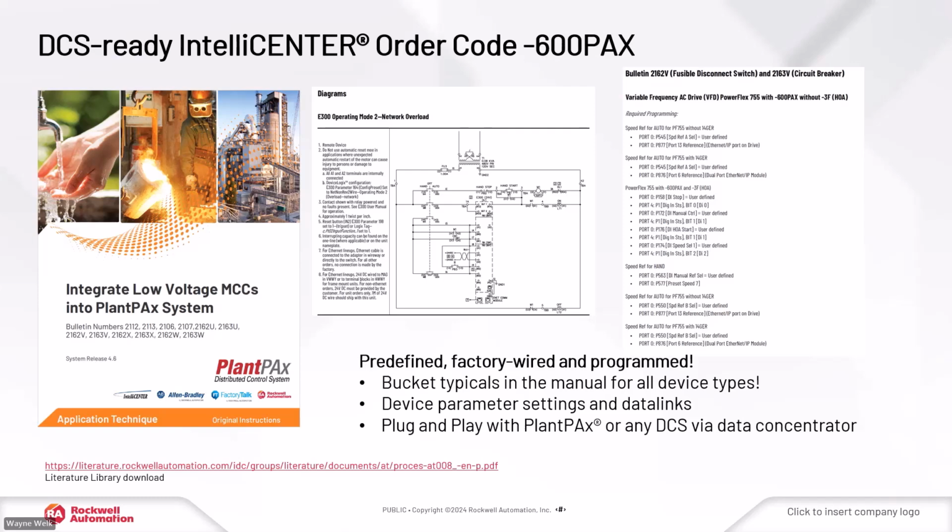So this is something that is engineered to order and will alleviate a lot of headaches down the road if you don't integrate your MCC with your DCS when you design the MCC.